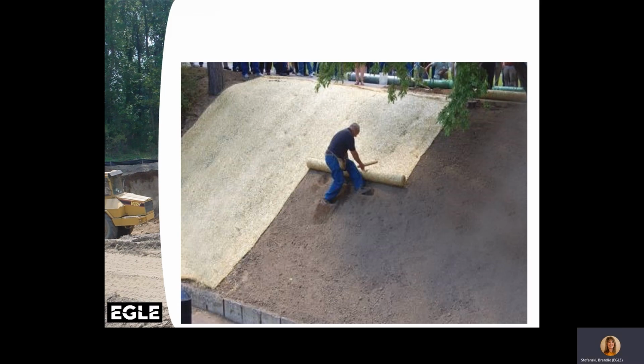Now we are going to discuss rolled erosion control products. Make sure the blanket type specified on plans matches its designated use. You need to check the rating for longevity, slope, and velocity. Is the material being used straw or coconut fiber, and is it biodegradable? Make sure the product specified is appropriate for the site condition.